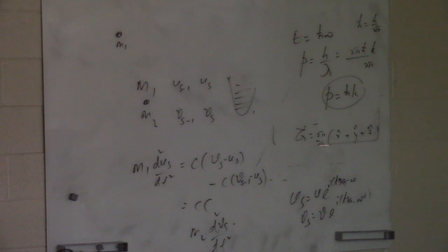But you cannot reduce it freely, because you still need to maintain higher electrical conductivity. So this is a very tricky problem, and there are a lot of ways people try to address it. Your electrons can pass through some areas, but phonons can get scattered. That means sigma is still not affected, but K can be reduced. So that's a very important thing.